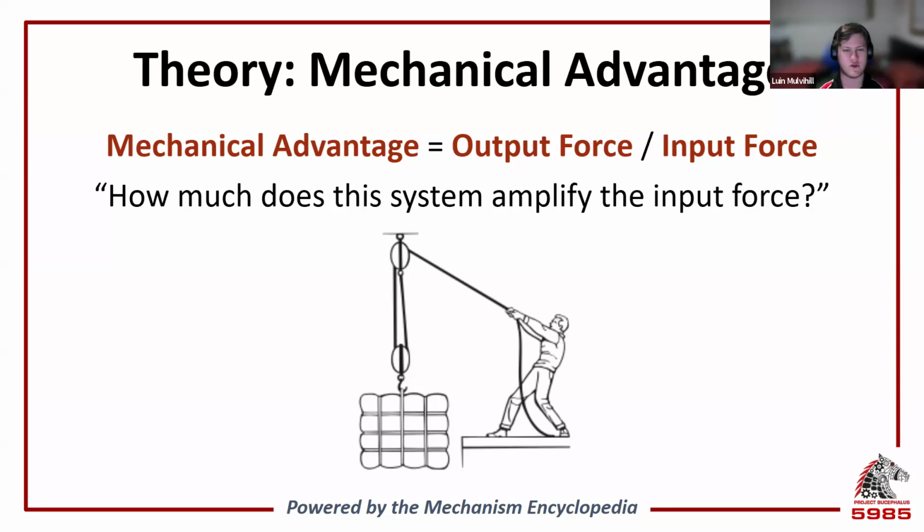This example shows a block and tackle system where you're trading force for distance in order to be able to lift a heavy load, i.e. you must pull twice as much rope, but it doubles the amount of force you pull the rope with. You'll find that due to the formula for torque, most simple machines function by trading force for distance.